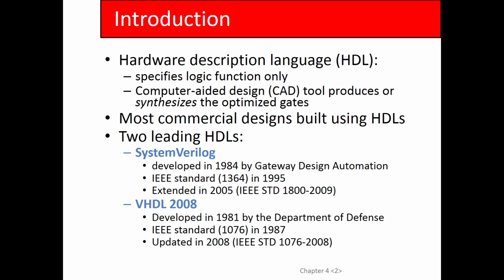Which means that if you have an HDL program, the order of lines in the program doesn't mean anything at all. Whereas if you write a Java or a Python program, the order of lines is of critical importance, because if you take a Python program and randomly scramble the lines, it won't work anymore. But with an HDL program, it will, because every line executes concurrently, just like every wire executes concurrently in a Boolean logic circuit. You guys with me?